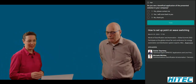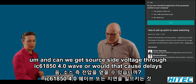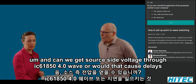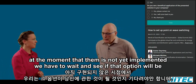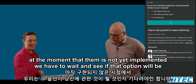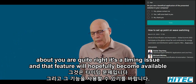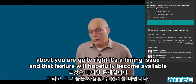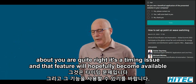Cool, great. And can we get source side voltage through IEC 61850 for point-on-wave, or would that cause delays? At the moment, that is not yet implemented. We'll have to wait and see if that option will become available. You are quite right that it's a timing issue, and that feature will hopefully become available.